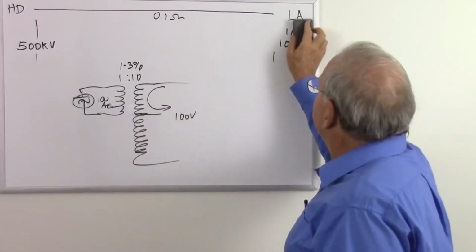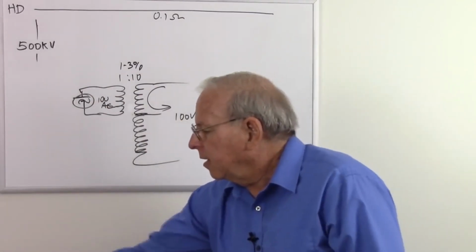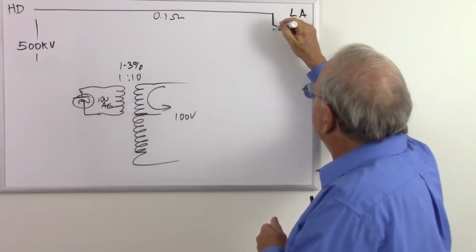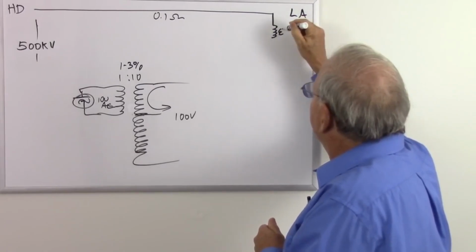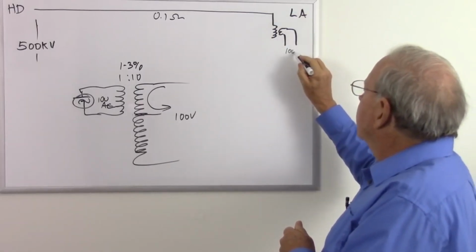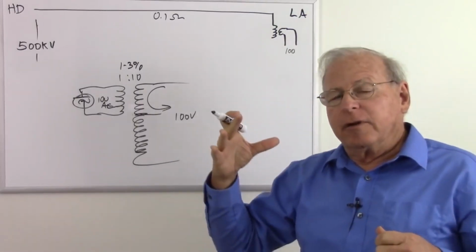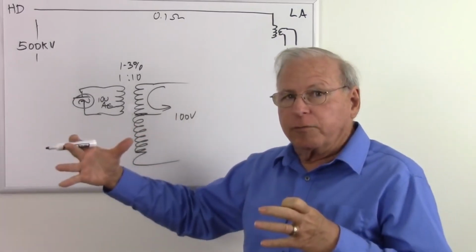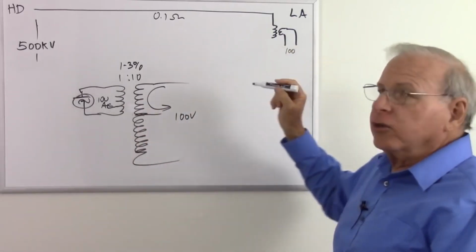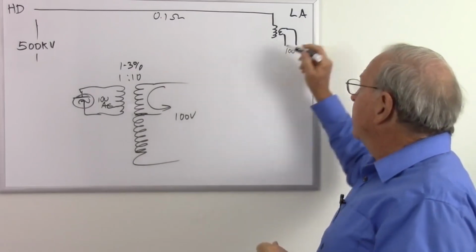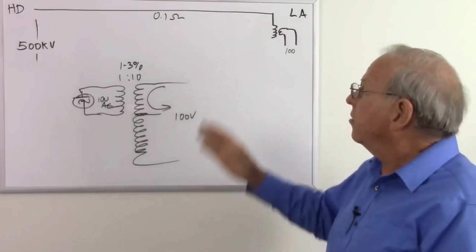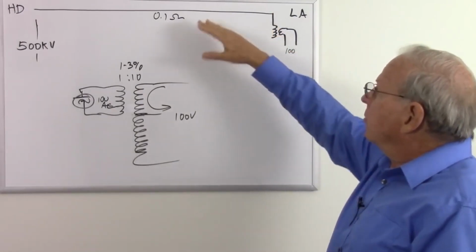So at this end in Los Angeles, I'm going to come down to a transformer, and actually multiple transformers, but I will transform it down to my lower voltage. I'll do it in steps. I'll step it down to maybe 230,000 volts for local distribution, then down to 10,000 volts, then down to 6,000 volts, 4,000, and eventually I get down to the 240 volts that is used in the neighborhoods, and then finally I get my 100 volts off of that. I'll talk about how that works later. But we have that step down there, and I can only do that with alternating current.